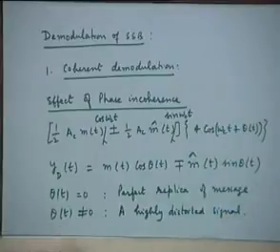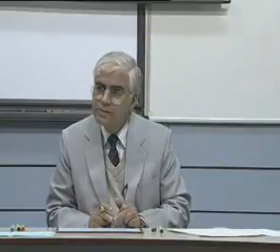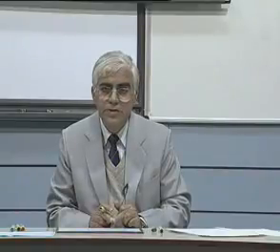So that shows that if I use a coherent demodulator for demodulating SSB signals, such a demodulator will be even more sensitive to frequency and phase offsets than the DSB-SC demodulation using the same demodulator. So that's something that you have to keep in mind. Now, fortunately, it is possible to effect this demodulation with better tolerance to phase and frequency offset, which can of course be removed by manual tuning, by another method which we shall discuss next time. Thank you.